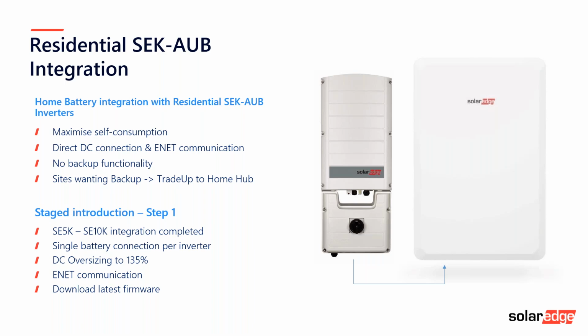The only key elements you need to remember are that battery communication must be EnergyNet, so wireless, no RS485 at the moment. And please make sure yourself or your Sparkies have the updated setup app, so they've got the latest firmware, which now supports this combination.